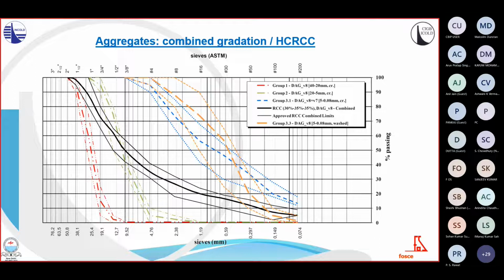example. In this figure, a second fine aggregate grading is also shown in brown, which corresponds to a typical natural washed sand that was used for conventional concrete in the same project. The difference between the RCC fine aggregate in blue and the CVC in brown can be clearly appreciated in both the shape of the curve and the significant difference in the area of the fines at the right bottom.